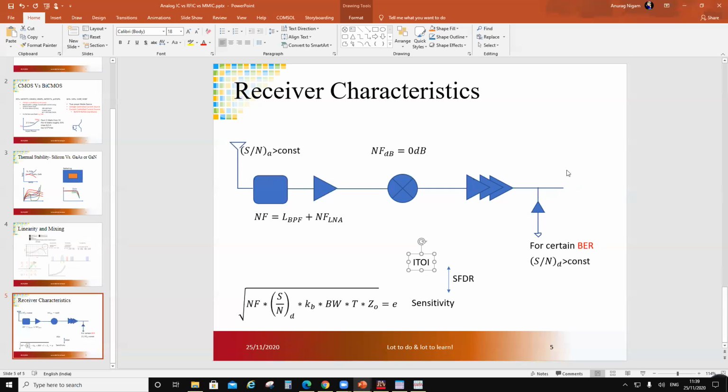Okay, so you want to cover the entire dynamic range of ADC. So that will be LSB and MSB. So basically you have a dynamic range of ADC. That's basically telling you what is the highest signal your ADC can achieve. And then from there, you find out what should be your input TOI. You don't want a distortion to be over here, right?